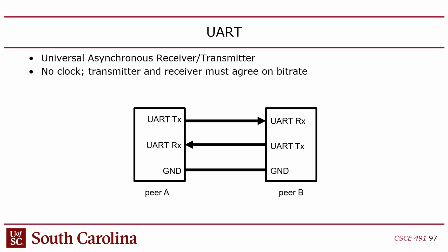Okay, so then just to finish up reviewing, UART, we started talking about UART last time. UART is also point-to-point. Generally, there's just 2 entities that participate in a UART channel. It's also bidirectional, which is equally as pointless as it is in SPI, because generally you're not doing bidirectional with UART. I mean, sometimes I'm sure there are cases where you can, but most commonly you're not. But you have a transmit on one end that's going to be connected to the receive on the other,